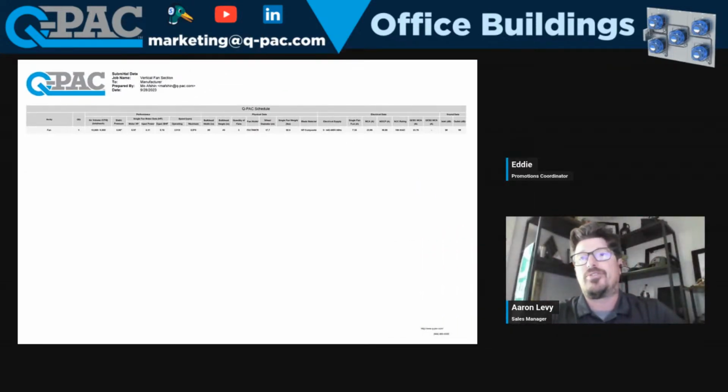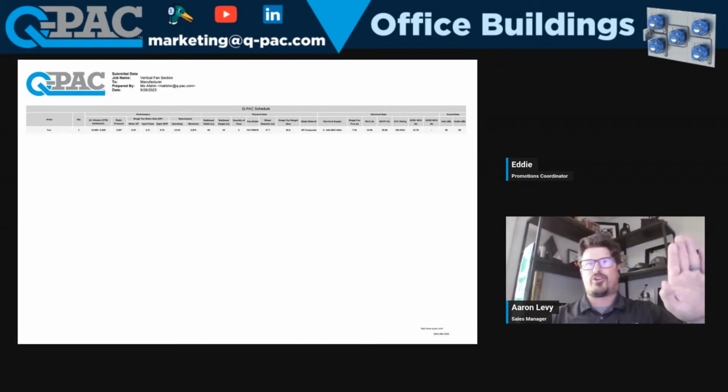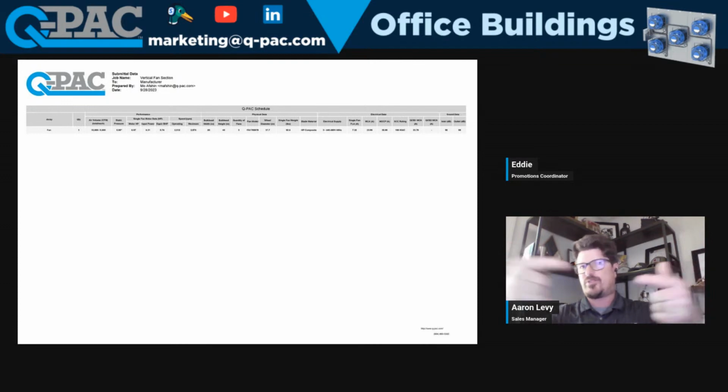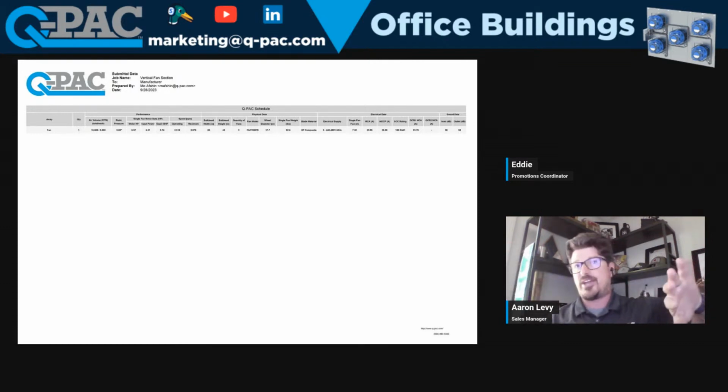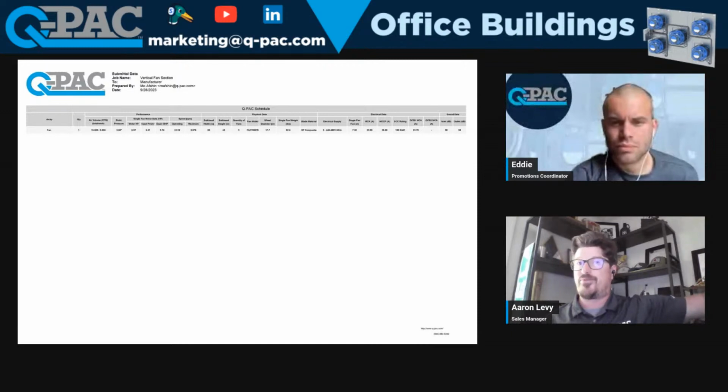Now, the submittals don't go into depth for the actual wiring process. That's all covered. In fact, the wiring diagram is the same for every system because it doesn't really matter. It really depends on how many quick connect boxes you have. So as long as, let's say you have 8 air handlers with all of them having less than 9 fans on there, the wiring diagram is exactly the same. There's only one terminal block in there that sends signals back to the quick connect box. Because it's a mirrored terminal, there's your line voltage and your control from this side to your line voltage and control on this side. They just have to connect those points back to back. And then we handle the wiring from the back side of that terminal block to the fans themselves.